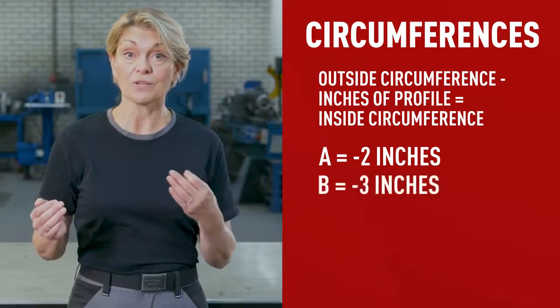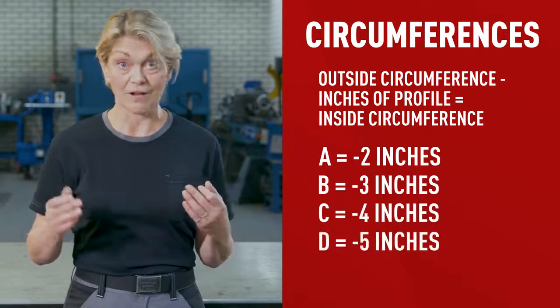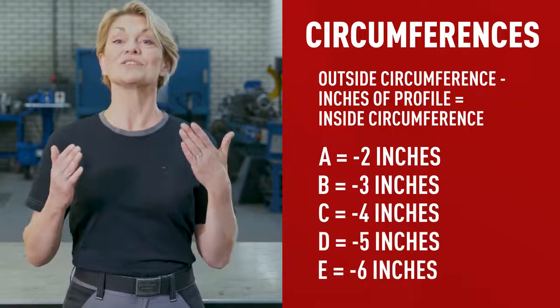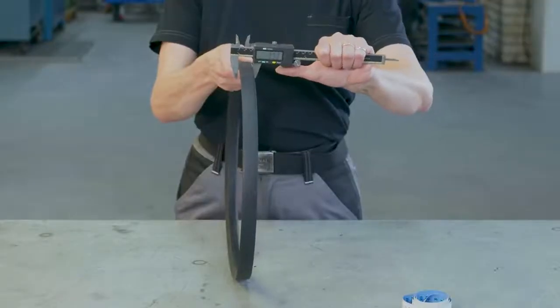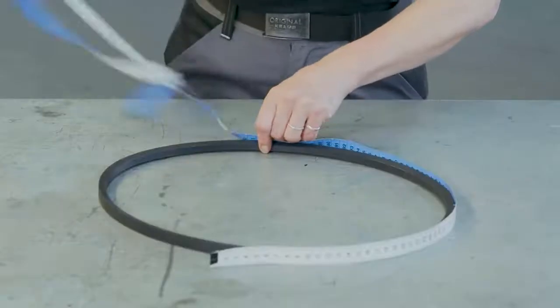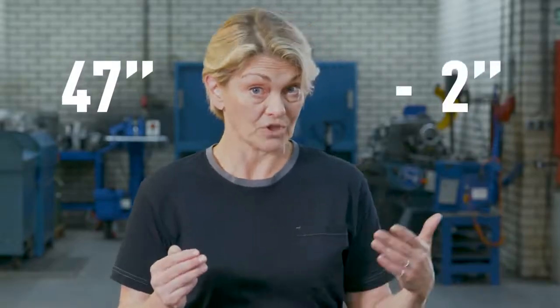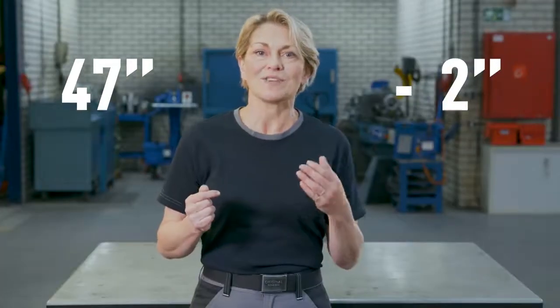For the B profile, you subtract 3 inches, C profile 4 inches, D profile 5 inches, and E profile subtract 6 inches. Take, for example, an A45 type belt. It's an A profile with a 13mm top width and an 8mm depth. The outside circumference I found in the previous steps is 47 inches. When we deduct 2 inches as per the general calculation rule, we'll find that the inside circumference is 45 inches, or 1,143 millimeters.